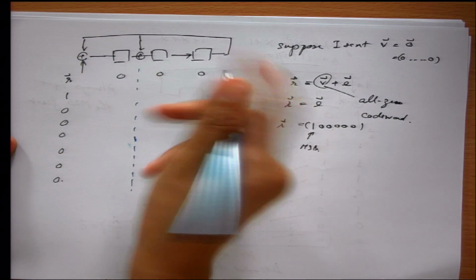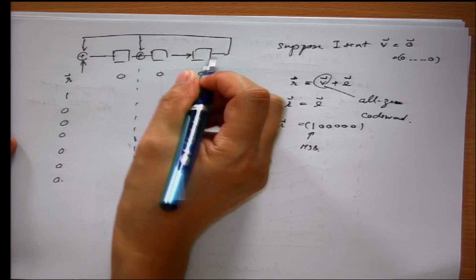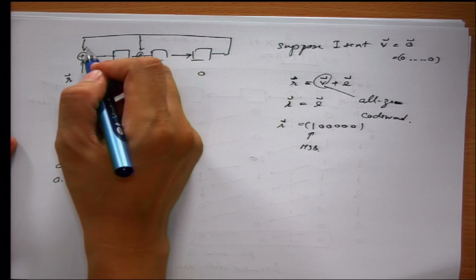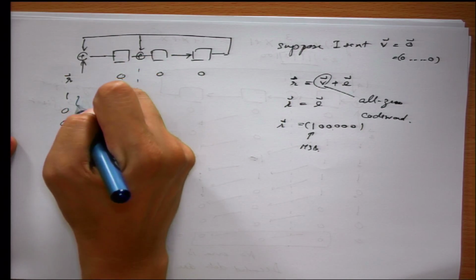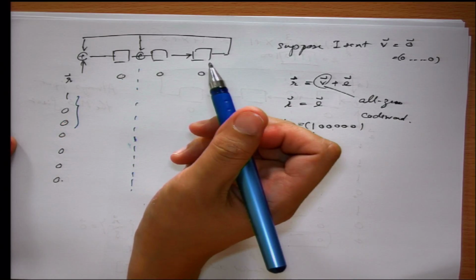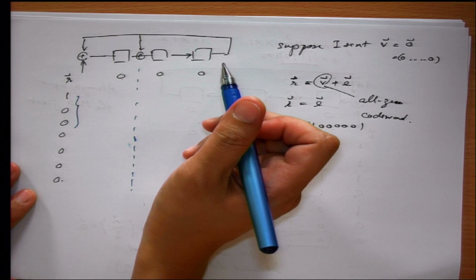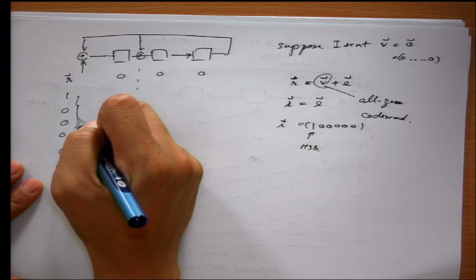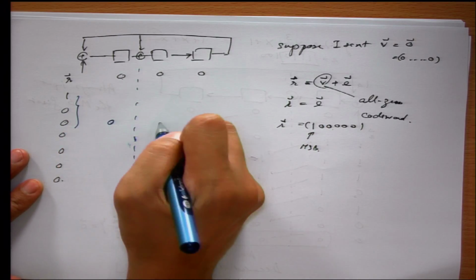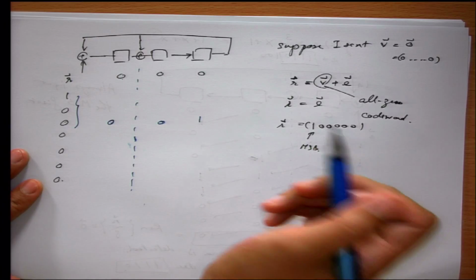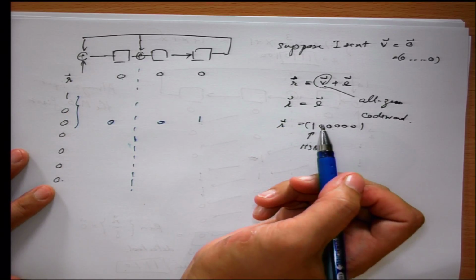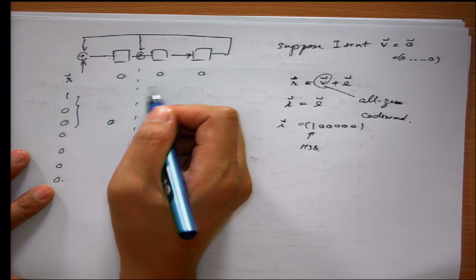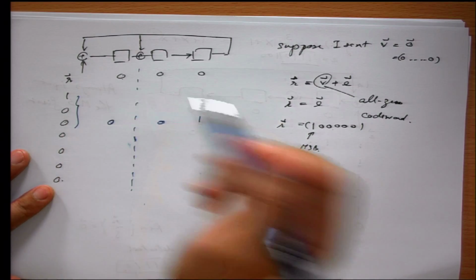Since these are all 0, it will shift in one by one, and the feedback is always 0. So for the first 3 bits, after the 3 shifts, you will always get this, because this one gets in and shifts to the back, and so on.